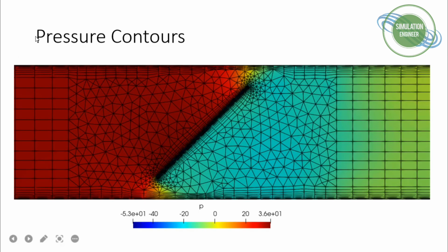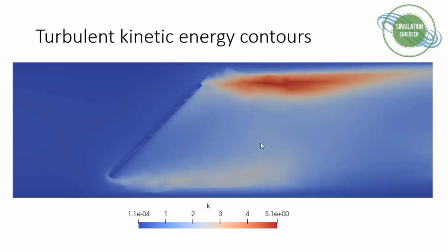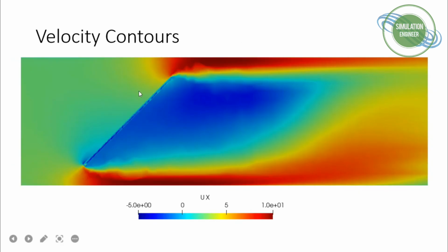And so you have pressure contours as we have already seen in ParaView recently. You have a high pressure region, and then you have a low pressure region. Obviously this region is really affected by the flow separation, but here it can be seen that there is an accelerated flow in these regions, and we are using our no slip boundary condition, and we have resolved the wall properly with prismatic layers, on the damper and the duct top and bottom parts. And if we look at the turbulent kinetic energy, it is also following a similar trend. If we look at this part of the velocity,